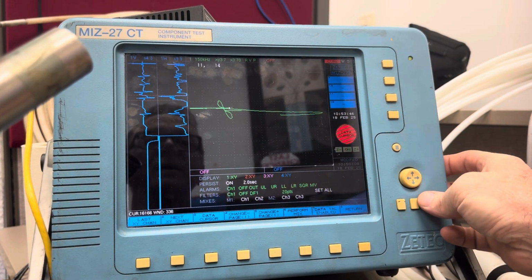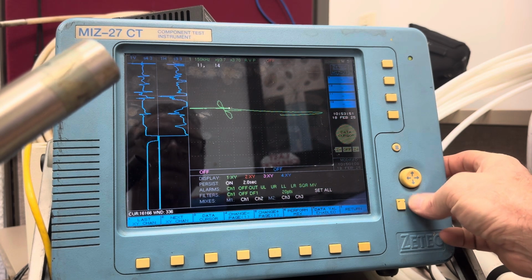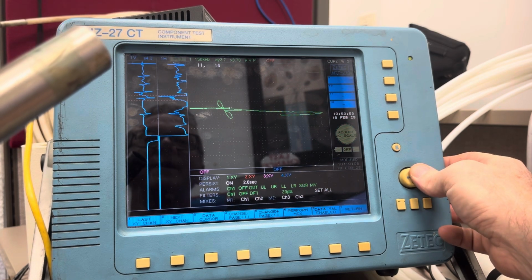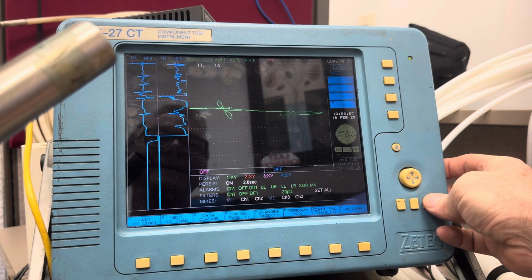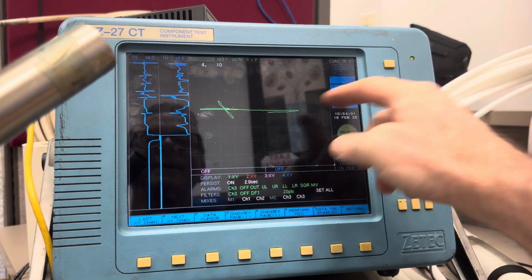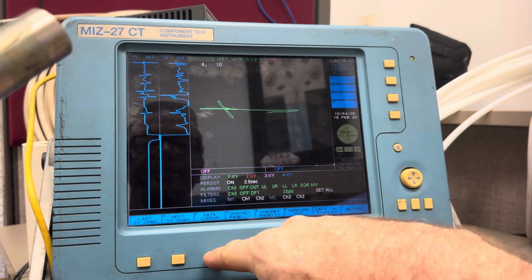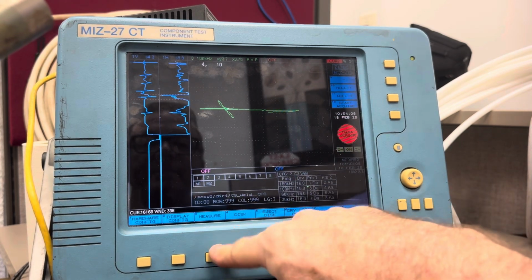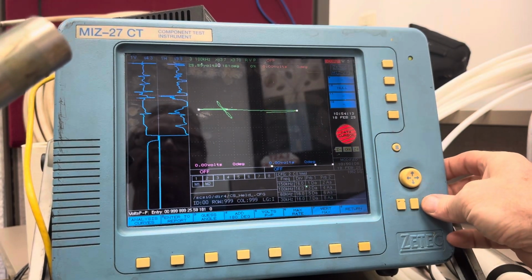Now let's go see if that rotates counterclockwise with decreasing frequency, like OD flaws do when you have an inside bobbin probe. My guess is it's not going to change much, only because I've seen thousands. Look at that. There's your 80, there's your dent. If you want to measure it, and go peak to peak, 181 degrees on channel 3.